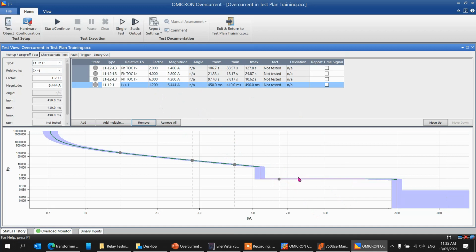So you are above the threshold. Because if you look at the setting that we have, I put 1 there, it gives you 5.37. So it's definitely on that line. So that's the setting that we did there. So 1.2 is a little bit over, so that you can see the trip over there.